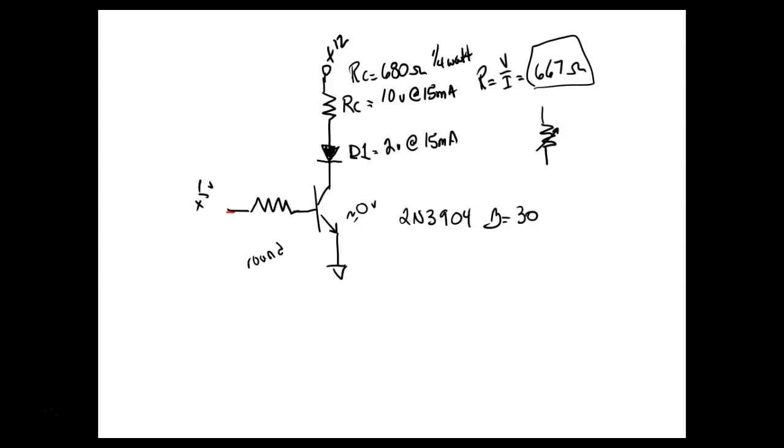So now we got everything we need. I know this guy over here. According to Kirchhoff's law, this is 0.7. We're putting plus 5 over here to saturate it. So how much is that resistor right there going to have to drop? 4.3. Good. We'll call this RB.